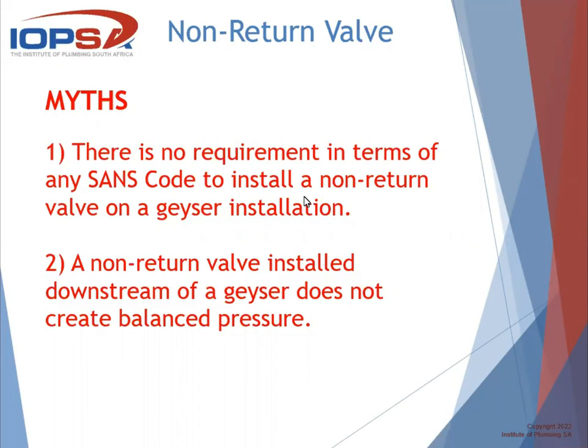And it must be pumped, but then you've got to control that pump. The pump has got to be controlled very carefully, either by differential temperature probes, or by timers, or by a combination of both, or by any other smart means. But the point is, it's got to be thought out and designed and controlled properly. Now, I've come across systems twice in the past 10 weeks where it's a brand new, beautiful, big home with a circulation system with 0 controls on the pump.